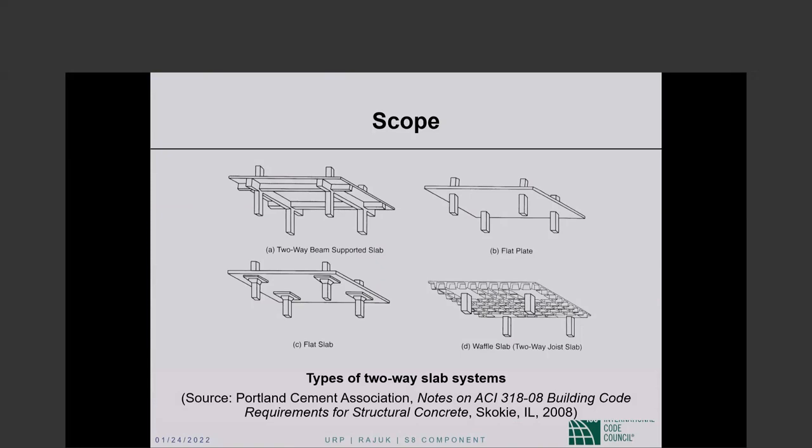Now, obviously, we do not cast a solid slab and then remove the tension concrete. There are ready-made formworks available for rent around the country that will produce that structure for us. This is called a waffle slab because it looks like the waffles that we eat. Notice that the slab around the column is not ribbed; it is solid, and that again is because of punching